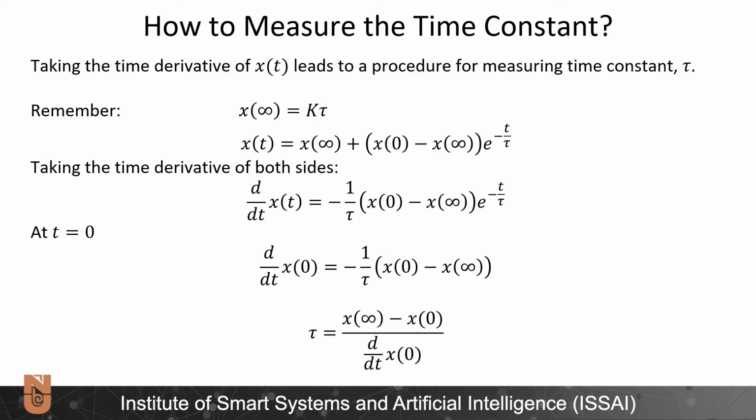How can I find the time constant of a circuit if I don't know what type of elements are inside? Actually, I can apply some type of DC voltage, look at the output waveform in the oscilloscope, and find the time constant of the circuit.